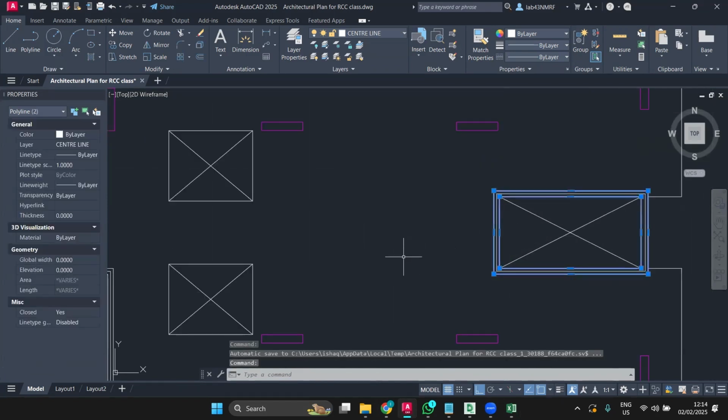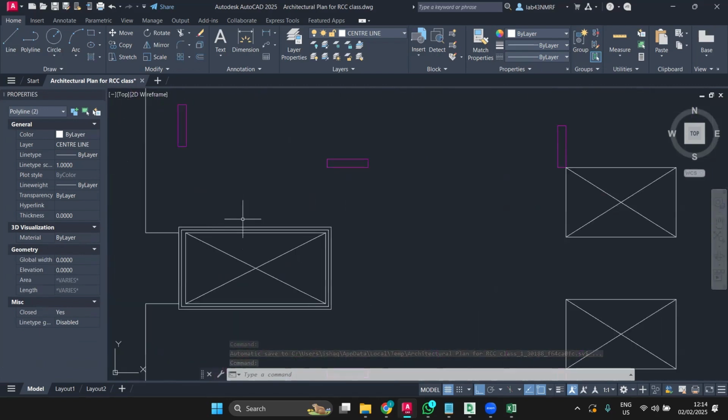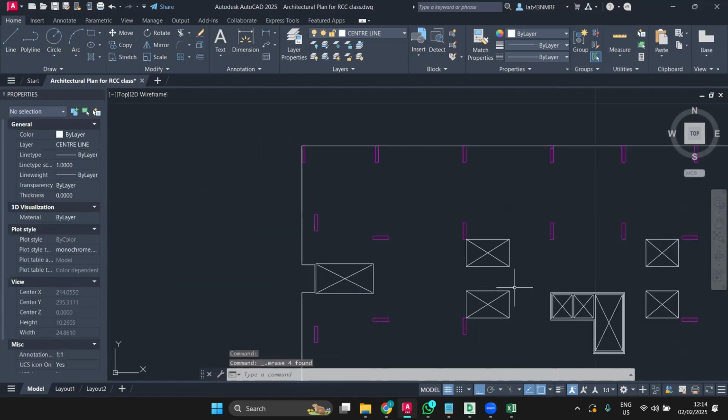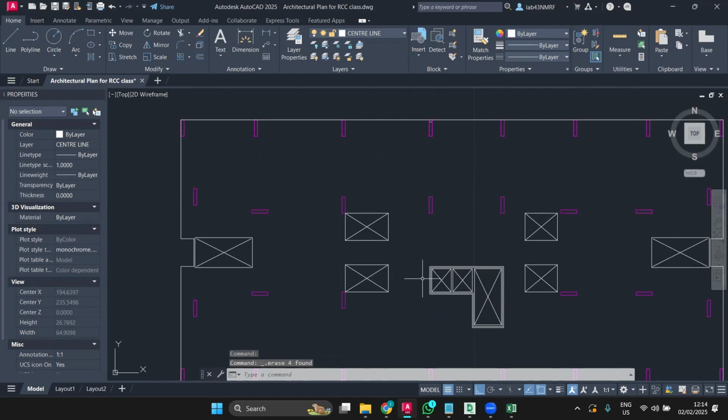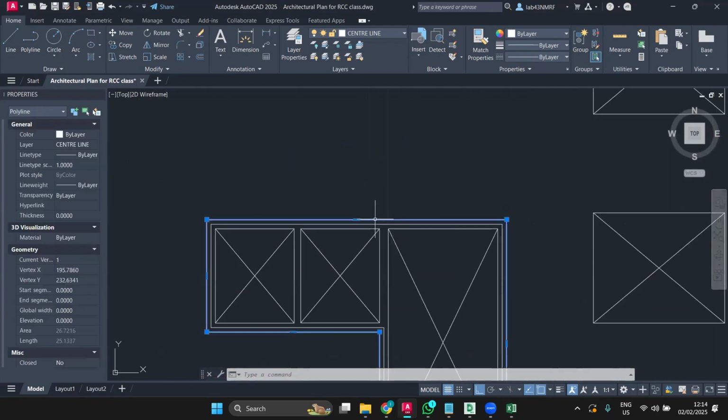What people have in mind is, I will keep all the walls and columns at 90 degrees. It is not so important to keep it that way. Then you're only focusing on one direction, and you're purposefully making the other direction weaker. So you need to focus on both directions. That is more important. Very good.